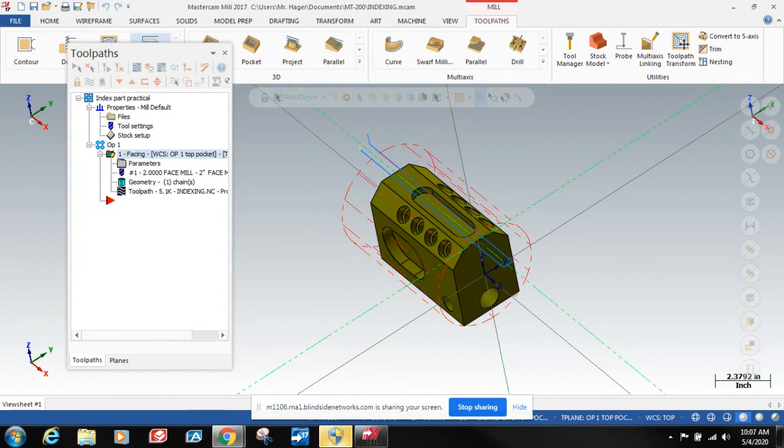I'm actually doing depth cuts, and what I'm going to do is face all 4 of the sides so that I have a square to work with instead of a circle, just to make it easier for myself. You're saying stock boundary not found. So when we set up our stock, it's 7 inches and then 5-inch diameter. Then the X is minus 7.0. Yeah.